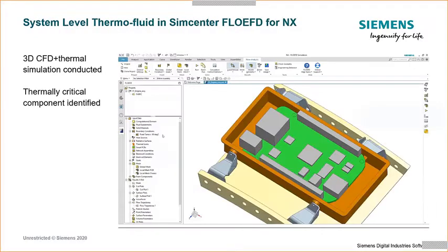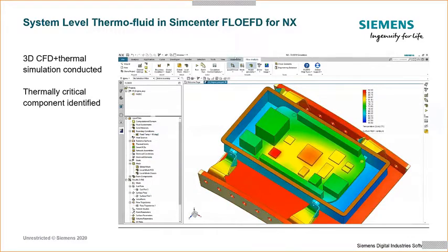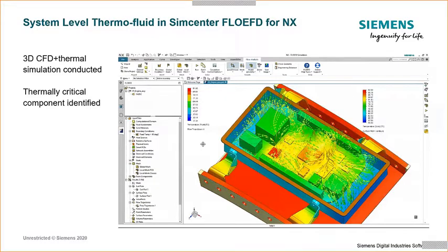Once it's in Simcenter FlowEFD, a standard thermofluid CFD simulation is conducted. And then once the solution is complete, surface temperature plotting can indicate the thermally critical component and also other surface temperatures in the model, as well as allow the inspection of the airflows, in this case within the FADEC enclosure itself. So that's the starting point, a system-level thermofluid simulation of the entire unit within Simcenter FlowEFD.